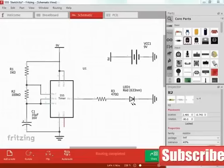Now I've already created a sketch in Fritzing for the 555 timer astable circuit. If you take a look at the schematic, there's a number of things that we can see here. Take for instance the battery. We can see that one end of it is connected to a 9-volt terminal and the other end to a funny looking symbol, which is actually the ground potential.